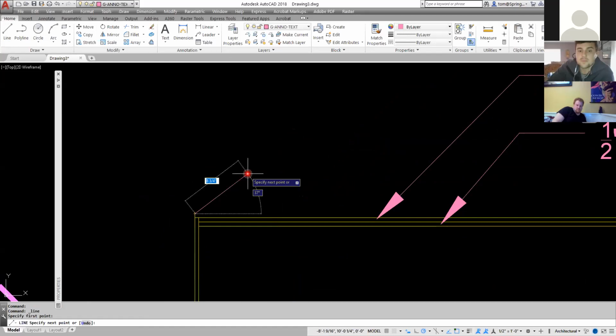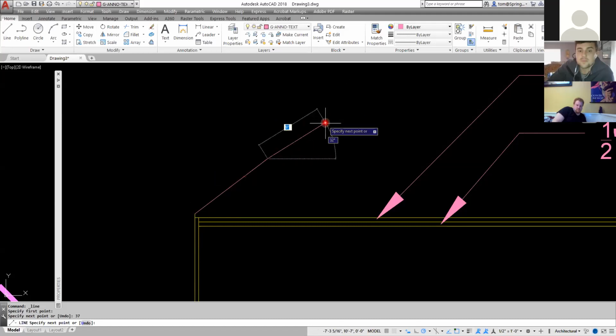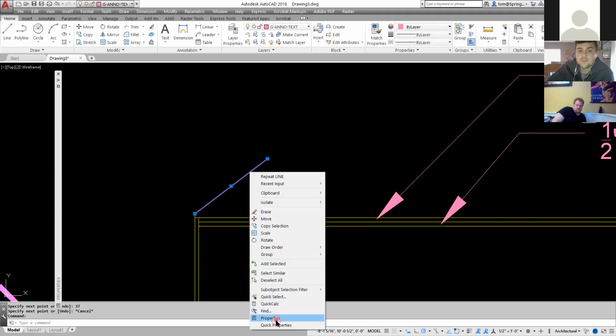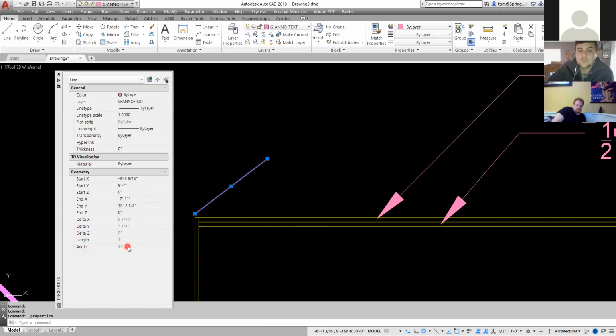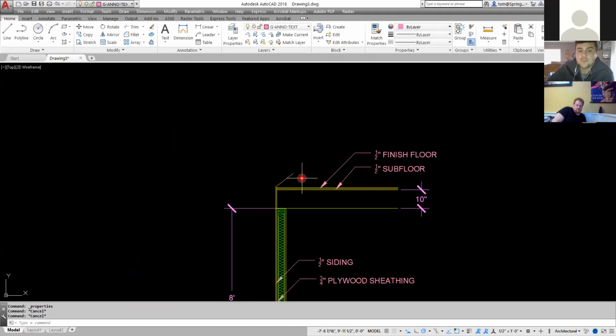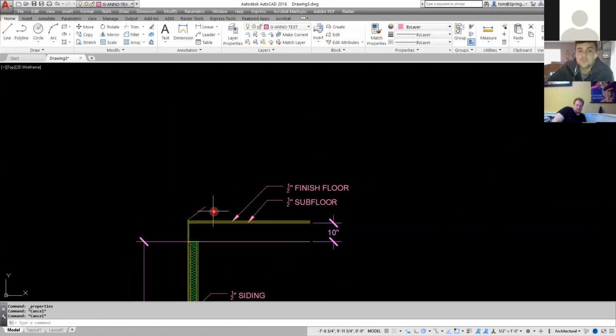I'm just going to go ahead and just to start it, I'm going to say 12 and hit my tab key. When I hit my tab key, I can now put in an angle, and my angle is 37 degrees. And I did that, and it gave me 37 degrees right there. So if I ask it what it is, it should tell me that that was 37 degrees, and does it? Yep, angle's 37 degrees, so I got that. I had it pretty close, but I went ahead and did that. Now, other than that, I didn't really put a length on it, so I just extend it.